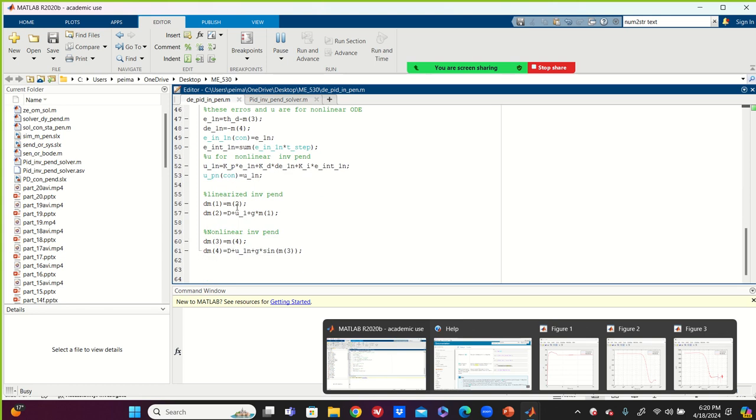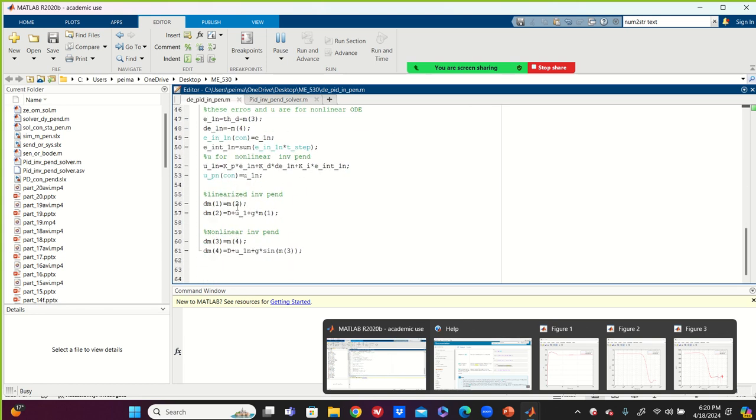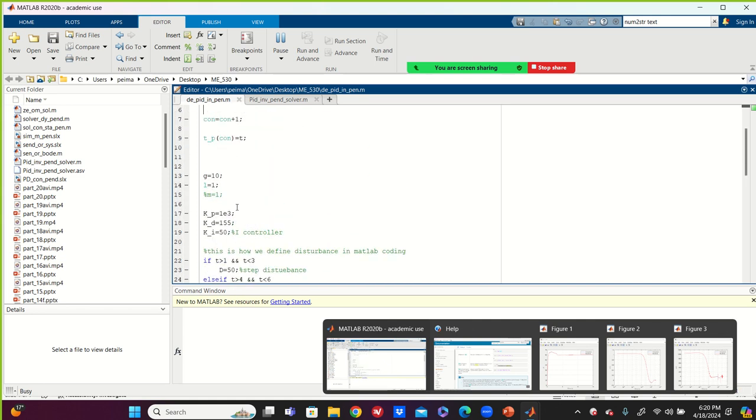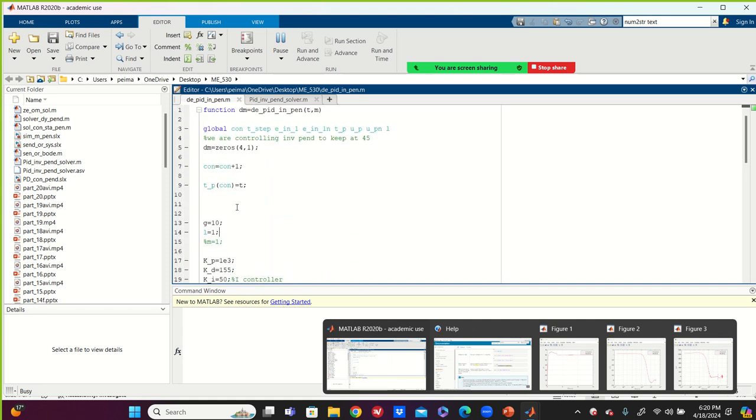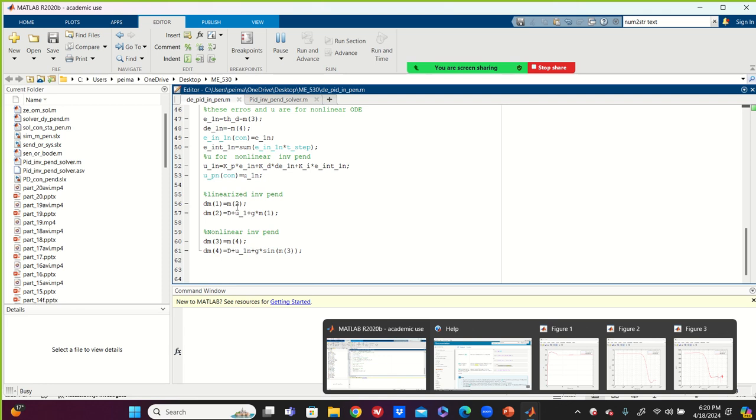You want to have a settling time of 9 seconds or a settling time of 55 seconds. For example, I was working for the US Navy on a project where the settling time must be 60 seconds for the valves. You're going to ask me why? Because if you close the valves very rapidly, it's going to generate cavitation. I hope that you read that in fluid mechanics. And cavitation over time is going to break the valve. So it depends on the application you have. See what I'm saying?